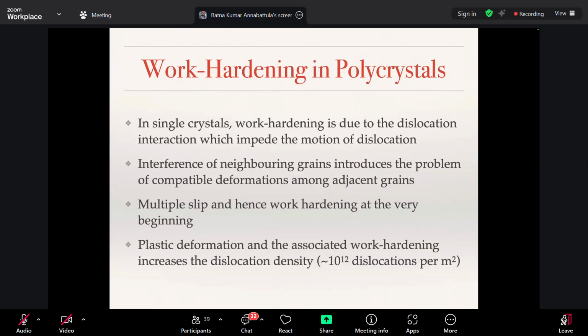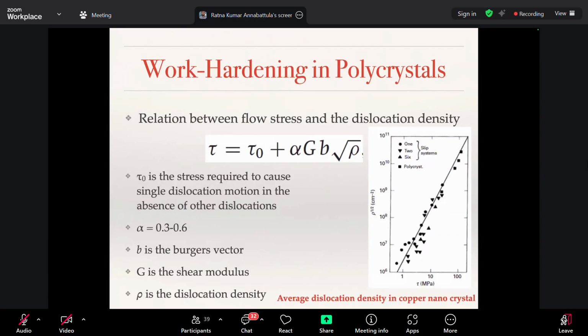Yes, sir, one question. So we are saying that in solid solution strengthening, the yield strength is increasing because of the impurity adding. In that case, like as we have seen before, grain size we are reducing, sir, in this case. No, grain size reduction is independent of solid solution strengthening.